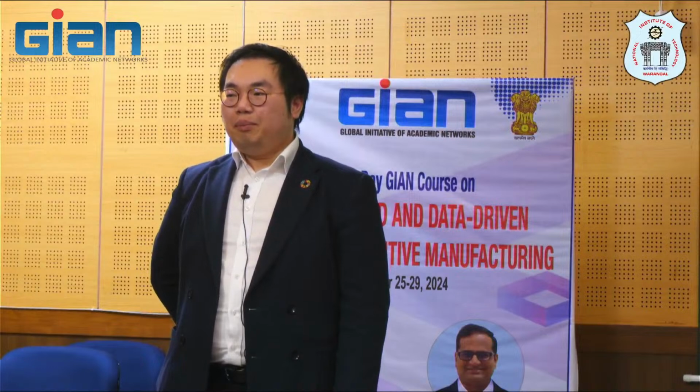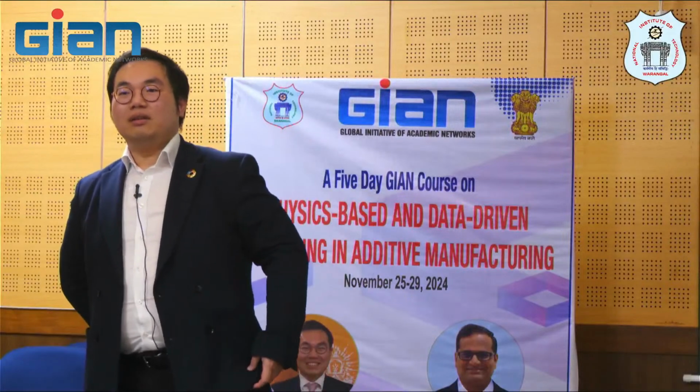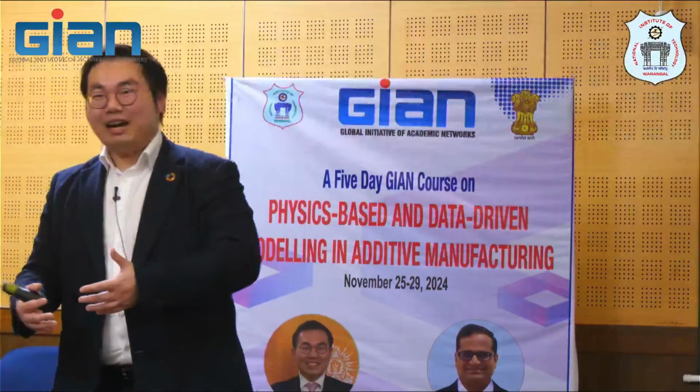Okay. Yes. But if it has some non-equilibrium segregation or solute profile, that may cause some impact. Because in just a short period of time, you can generate a big residual stress because the element segregated to the boundary, and this may cause the cracking. Because as you know, you're not printing only one layer, you're printing several thousand layers. Some layer below may already have what we call intrinsic heat treatment. It's heat treated somehow already. So at some point you will get some effective ductility dip due to that underneath thermal cycle.